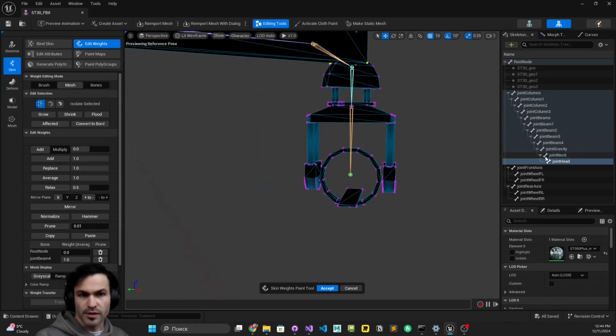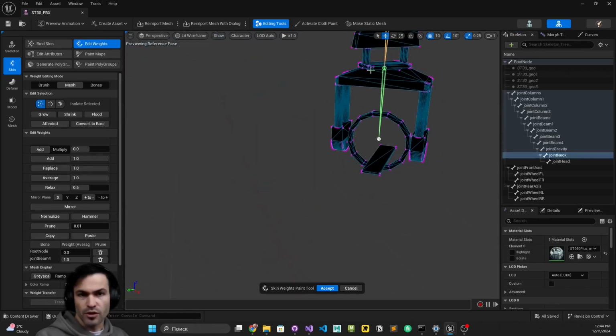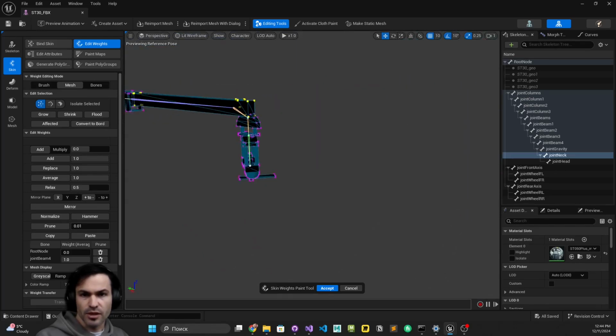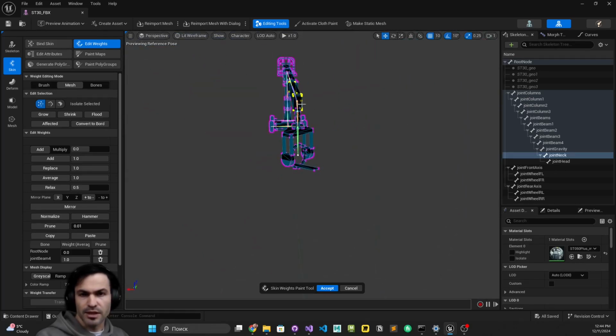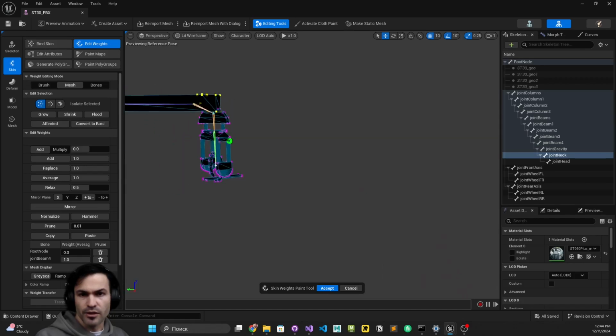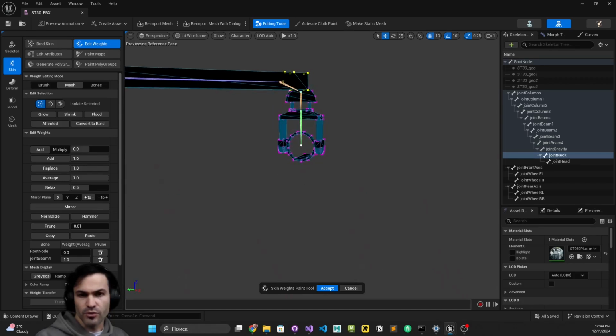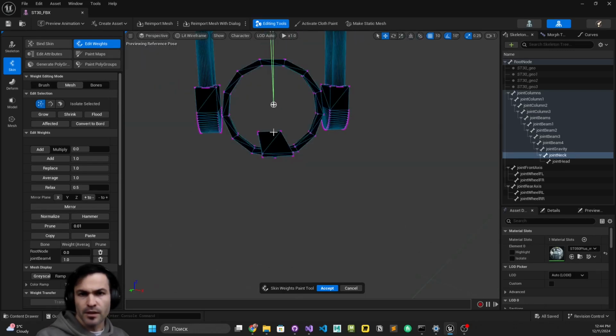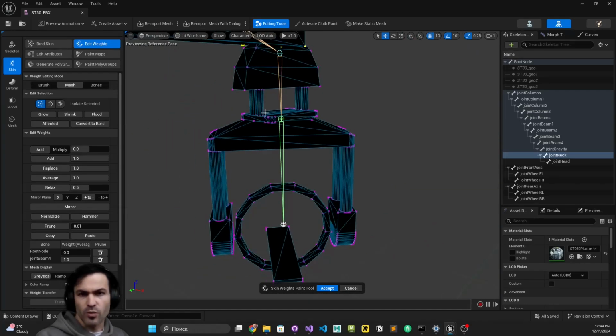So for example, this is the neck joint. It should be rotated in one axis, like a horizontal rotation. And the gravity bone should be rotated in this direction, just depending on the tilting of the angle. The gravity bone is always trying to keep the camera alignment upright. So these are the associated weights we have to assign.